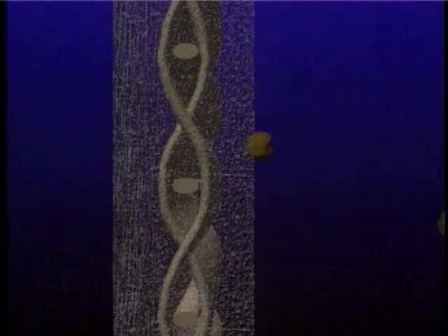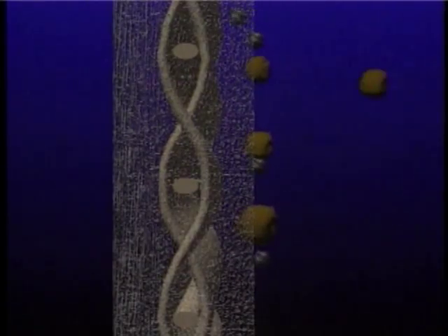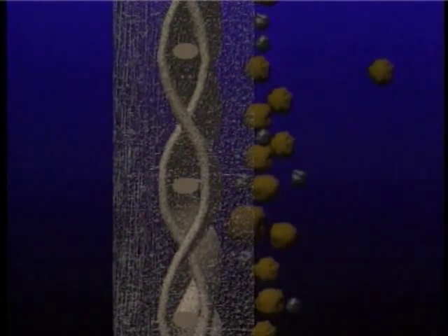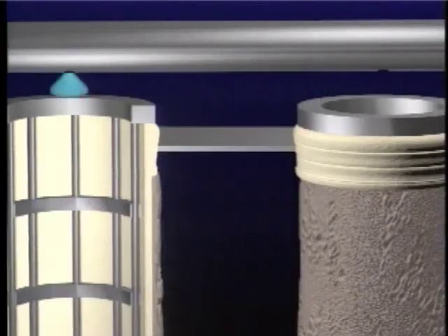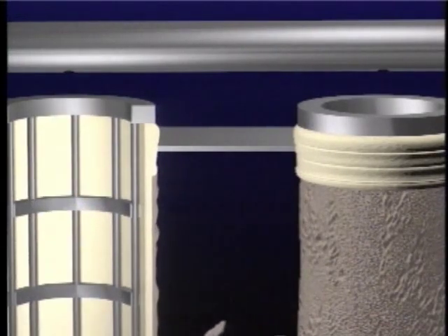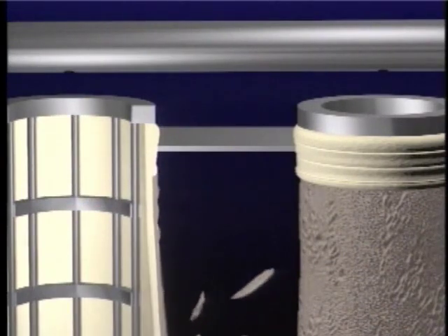As with woven fabrics, the collector's ability to remove small micrometer and submicrometer particles is due to the accumulated dust cake and not the fabric itself. The fabric is usually pulsed several times an hour to remove some of the dust cake, but may be pulsed much less frequently when the dust concentration is low.